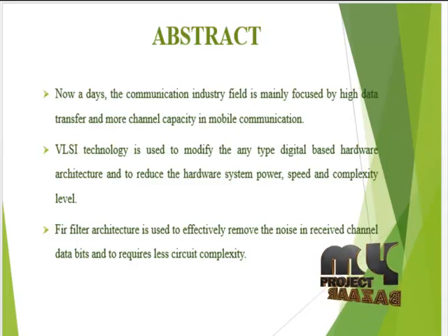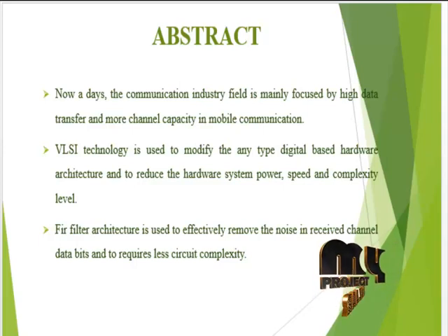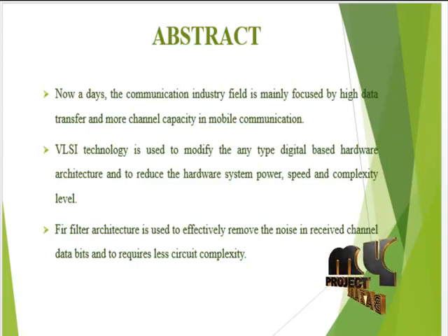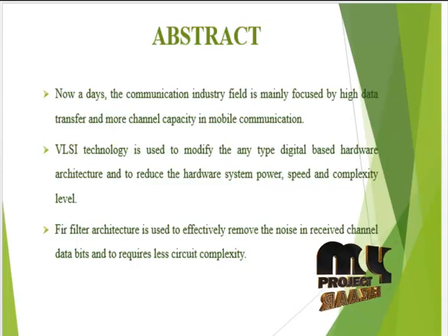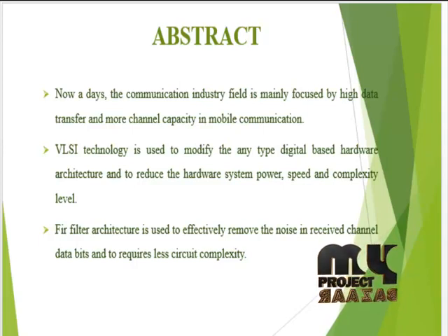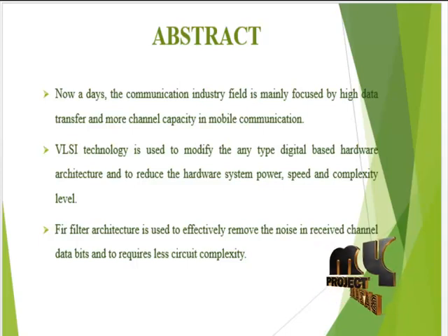Most of the designs and implementations of FIR filters so far focus on the optimization of the MCM block. Now we have observed that the product accumulation section often contributes the major part of the critical path, such that optimizing MCM blocks has little impact on the overall speed of the FIR filters. And then we have referred to benchmark FIR filters and the critical path delay of the corresponding MCM blocks.